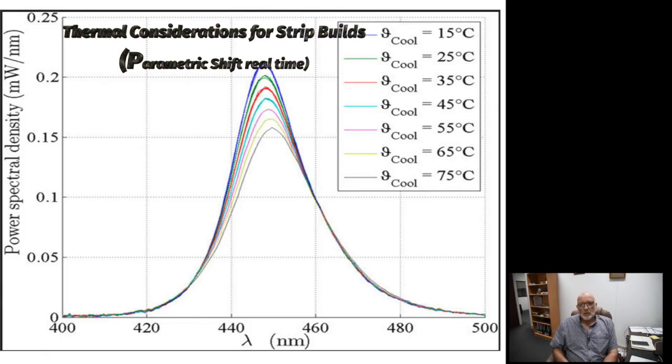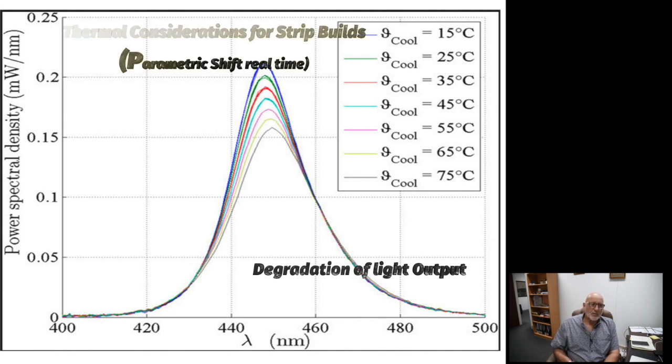Most folks will read that as lumens per watt, but for grow folk it should be considered in terms of micromoles per joule. So what I've got is three slides that are pretty useful in demonstrating those particular issues. These slides are LED tests based in real time, so the information is based on taking a single LED, driving it, and then generating some key metric data about thermal performance. So let's consider first what occurs in real time, and later we can talk about lifetime data and what happens over time, which I'm sure is more important to you as a builder than the immediate impact of when you first turn your grow light on.